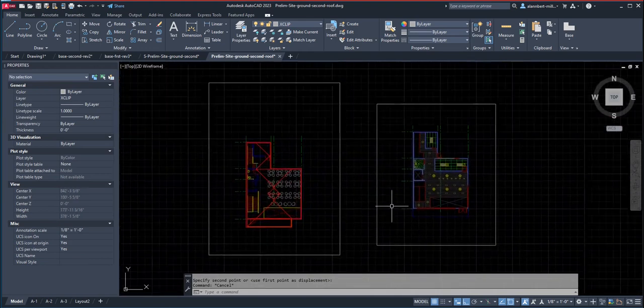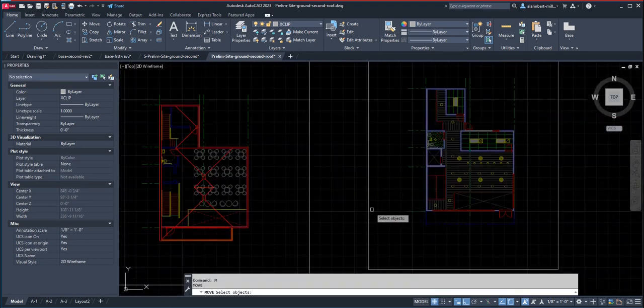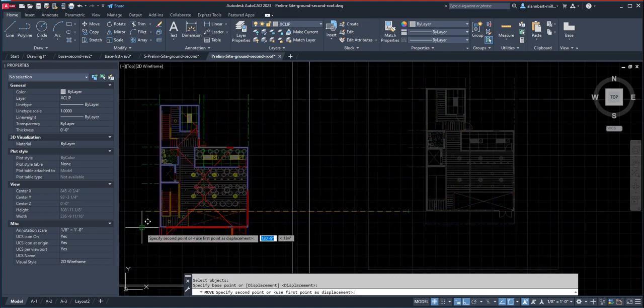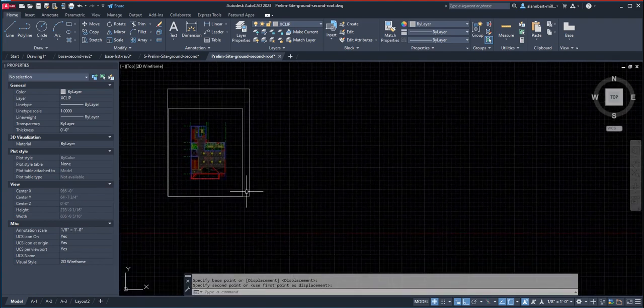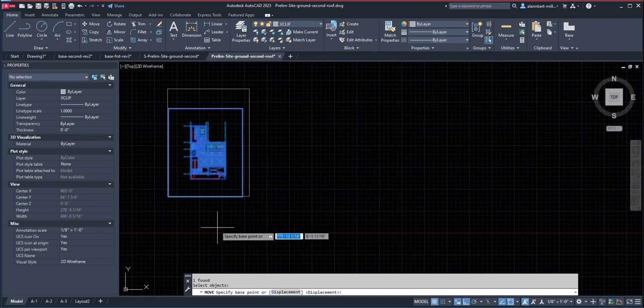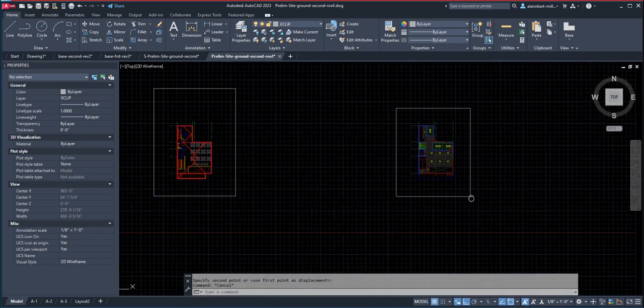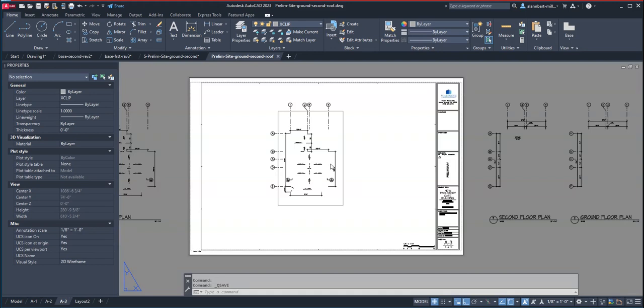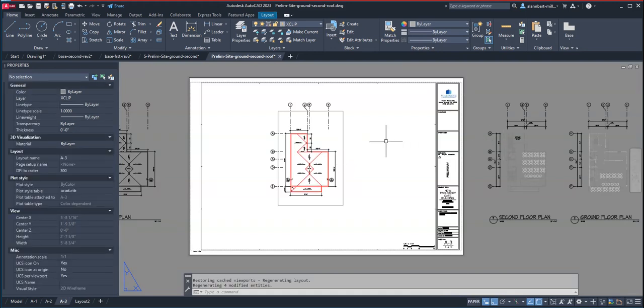And then I want to align this viewport with my endpoint here and endpoint here. There you go, they're aligned now. I'm gonna move that previous again and move that further to the right. Okay, so that's my reflected ceiling plan. I'll save that, then go with my A3, and I know that my reflected ceiling plan is simply to the